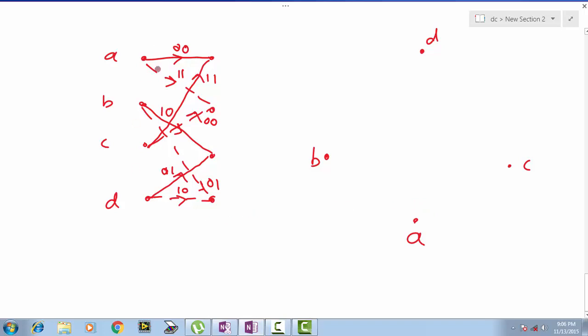Now if you see clearly, when input bit is 0, that is a solid line, we are moving to the same state A, and the output is 0 0. So arrow mark. When we are in state A, solid line represents input 0. We are moving to the same state with output of 0 0. Now when we are in state A, if the input bit is 1, we are moving to state B with output of 1 1. So draw a dashed line, and output is 1 1.